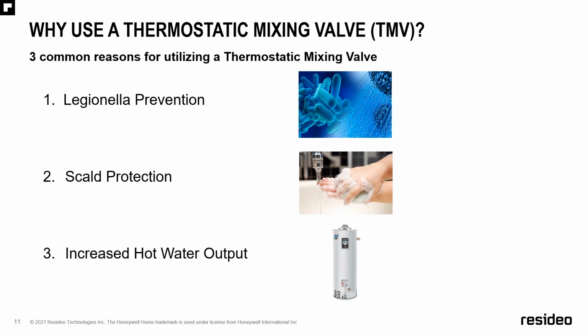Legionella showed its ugly face way back in the day when we were storing water on top of buildings without any kind of recirculation, where it was just sitting stagnant. It will not only grow, but multiply very, very quickly in those types of applications. And that can actually hold true in tanked water heaters. So we'll talk about why mixing valves will stop that from happening.